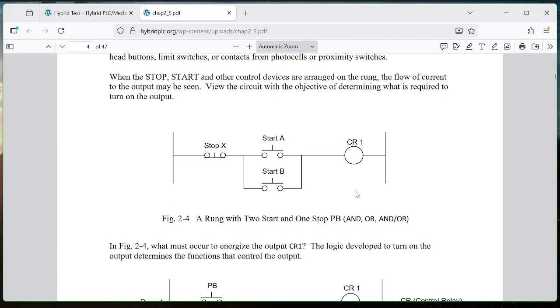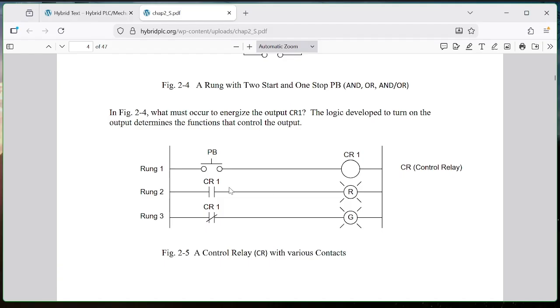All right? Now, these relays have contacts on them. You see those and you hear them. When you hear that clicking, those are those contacts going open or closed. Okay? Now, this is a normally open contact. That's not a capacitor. As I said the other day, that's not a capacitor. That's a contact that when you energize, it closes. Everybody got that? This one is a normally open contact.